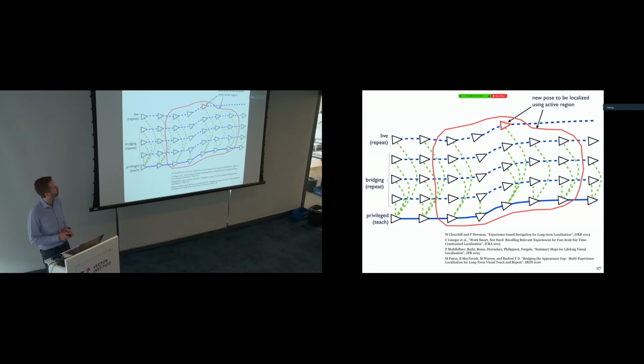So basically what we've done is we've taken this relative pose graph structure, where I've now removed the landmarks because it's a bit too cluttered if I leave them. And the first time we repeat is here, and now we have 2 experiences in the map. Then the next time we have 3 and 4, and eventually we have 5. And now we use the same rubber banding trick that we did before, only now instead of just a spatial pose graph, we have what we call a spatiotemporal pose graph.